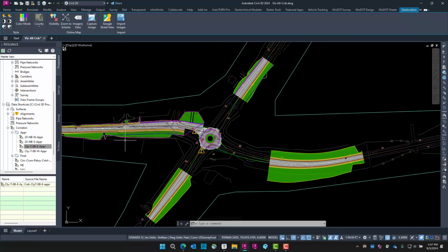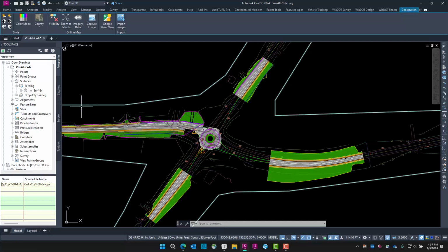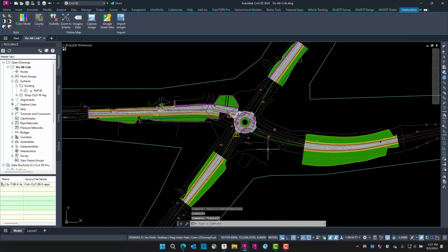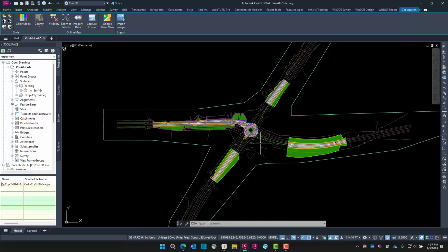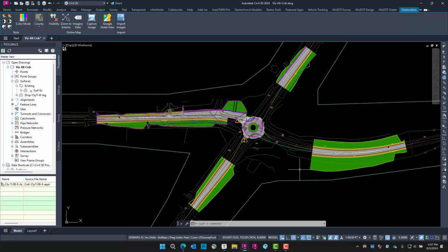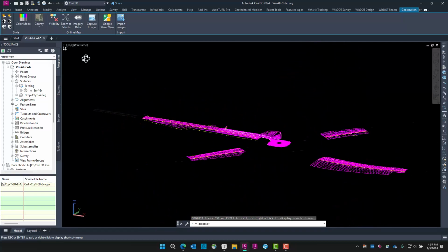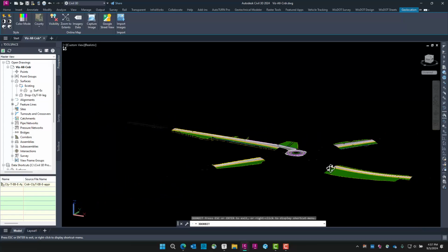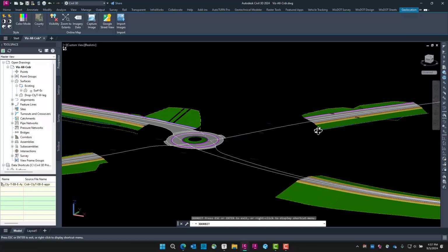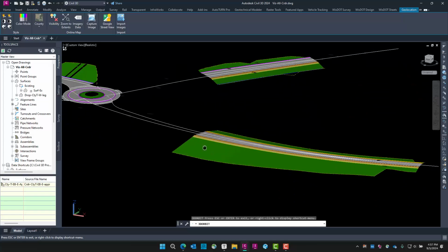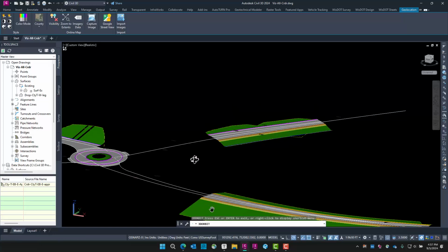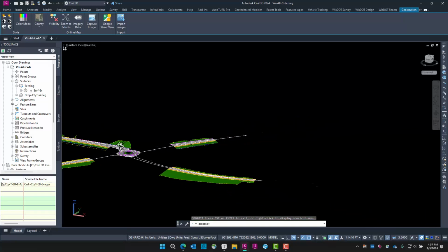Now, that's all great. I hope I've got the existing surface. Yep, existing's in here. So this is my border for existing surface. And as you can see, I've got a XREF of my existing topo in here. So I might be able to show somebody who's not a Civil 3D user this, and I'd certainly be able to go to a 3D orbit, grab one of these, do a rotate, and change my style to a realistic. Remember, I'm not going to get those renders unless I do. And I've got some surfaces now. I can see that these two legs are pretty decent fill. We're kind of scratch grading, not surprising, with just an intersection here, and we've got some cut area too.